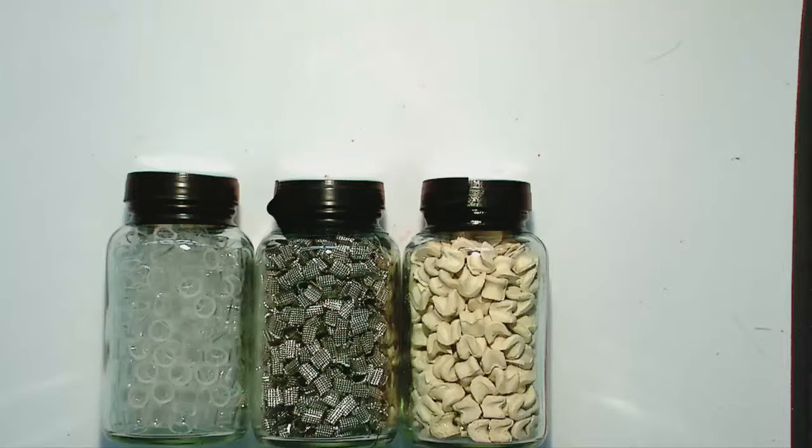So this is a glass packing, a borosilicate glass packing, okay? So you might use that for a very reactive system, because glass is very non-reactive. This is a metal packing. Okay, it's often the cheapest type of packing, but if you've got any liquids in your system that might be slightly reactive, then they're generally reactive with a metal, so they may start to degrade or erode or actually completely destroy your metal packing. And then the final one is a ceramic style of packing, and ceramics are very good at very high temperatures. So if you're having to do a separation at very high temperatures, then you might want to think about a ceramic style of packing.